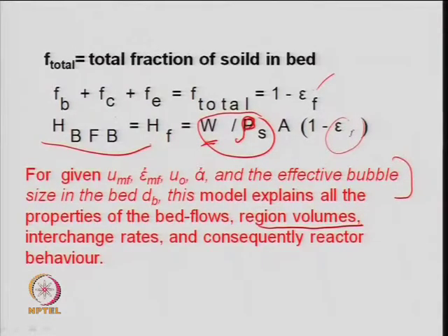But there are a lot of further complications when you look at the hydrodynamics. You have to study RTD to get the mean conversion. For different size particles, you have to find out their average length of stay, and then there may be elutriation, some of the particles may leave the bed. So, all these complications will be there when you look at a fluidized bed reactor design. But once you have an efficient design for better heat control, when the reaction is highly exothermic, it is a good type of reactor system, because it has the combination of a mixed flow and a plug flow.